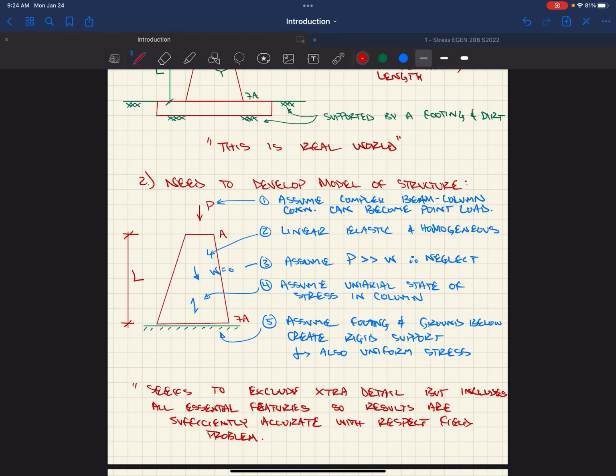and stress. If we were looking at thermal properties, that would have changed the way we made the simplification to the model in the first place. We'd want to be very accurate with respect to the material. The rebar is going to affect how our, say, thermal conductivity works across the column and things like that, and that would have changed our simplification. So it all comes back to what are we really after? We've got to think about that first.